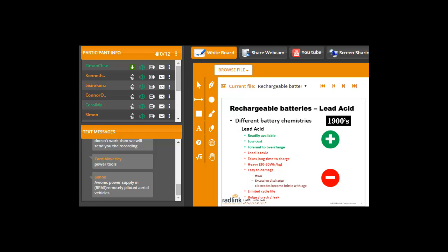And the best part is there's no discharge-charge memory effect. But again, it has terrible self-discharge characteristics, and it's a very limited cycle life. So you might find only 500 cycles and you need to change them out. And the charging time is slightly longer because of the chemistry.